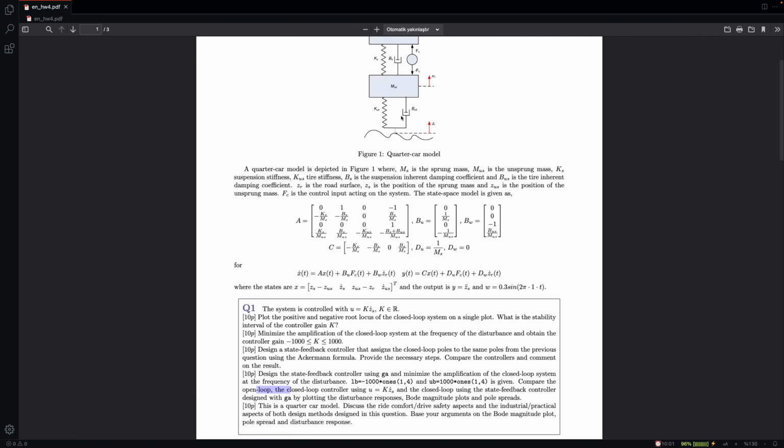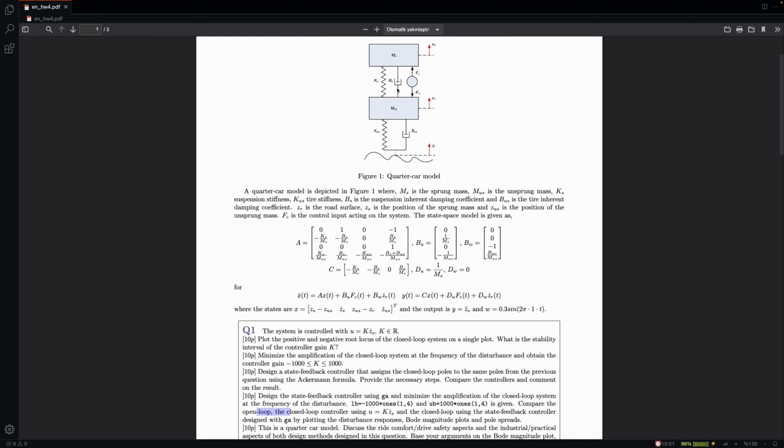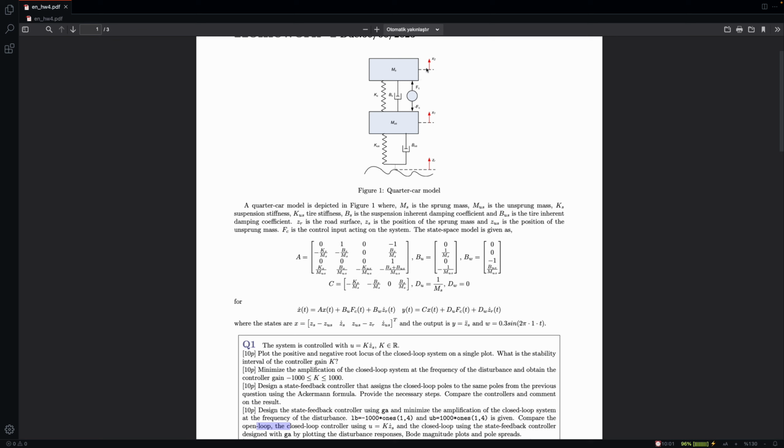By the way, why do we need to optimize our controllers or our system's acceleration? Because this is acceleration here, what we are trying to minimize. Here we have the acceleration as the output, the upper body acceleration in this direction here. It is important because if you're a passenger or driver in this vehicle, you will experience this acceleration, and in terms of comfort, this is discomforting. If the road gets messed up quite much, then this is discomforting, so you should basically try to optimize that.